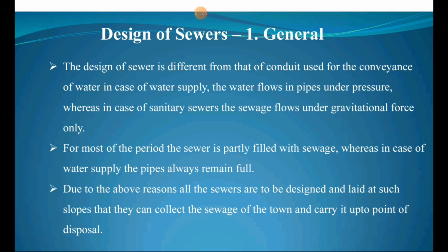For most of the period the sewer is partly filled with sewage, whereas in water supply the pipes always remain full. Means sewage is not running full in the sewers, however water is running full in the conduits of water supply. And due to the above reasons, all the sewers are designed and laid at such slopes that they can collect the sewage of the town and carry it up to the point of disposal.